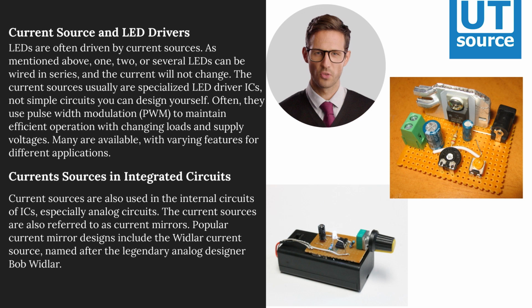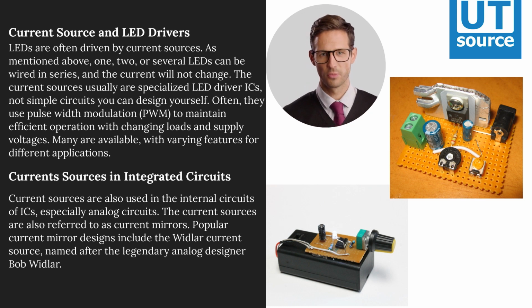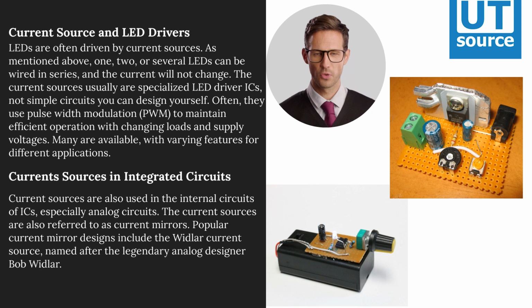Current sources in integrated circuits. Current sources are also used in the internal circuits of ICs, especially analog circuits. The current sources are also referred to as current mirrors. Popular current mirror designs include the Widlar current source, named after the legendary analog designer Bob Widlar.